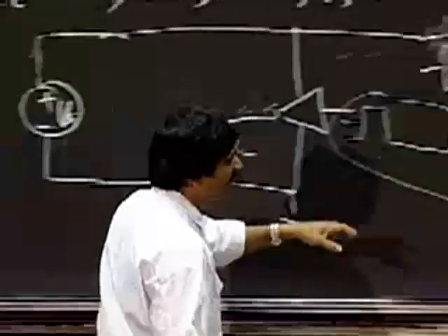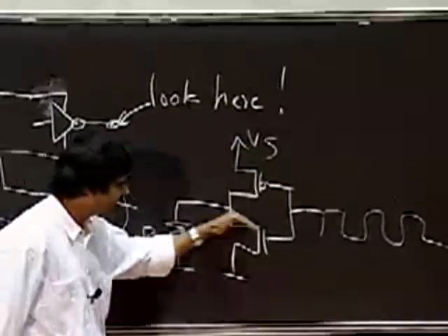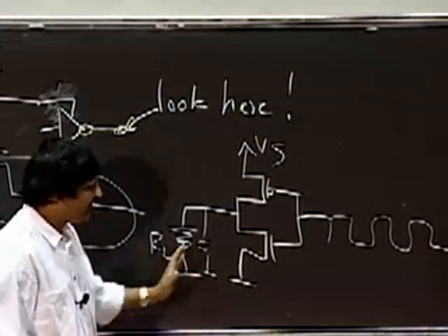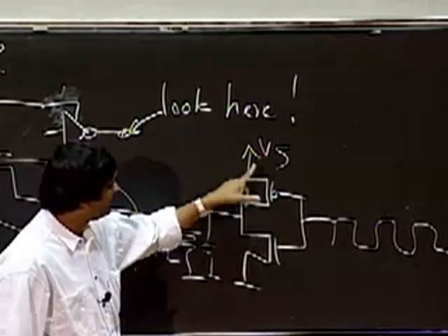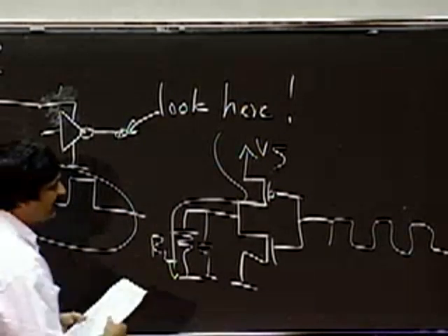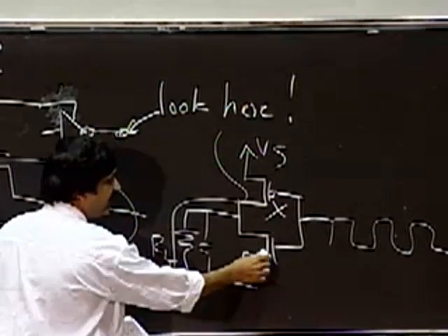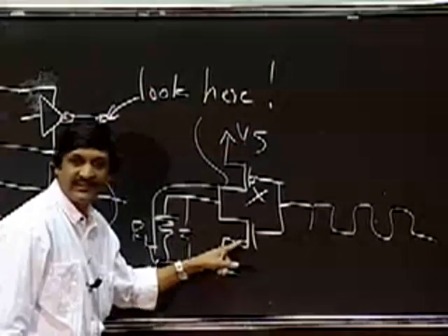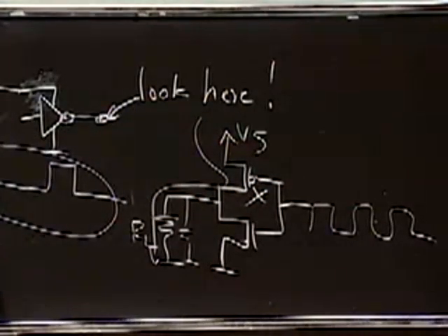Okay, so just remember, what's the signal doing? The signal is high. This guy turns on, and current flows like this. So let's say I have some sort of a capacitor here. This charge is like this, and when it's low, the P FET is on, and current flows through here, down here. And then when this goes high, this guy goes off, and this guy turns on. Okay, so the current flows out this way and discharges through this guy. When I turn it off, the P FET turns on and draws current from the top.